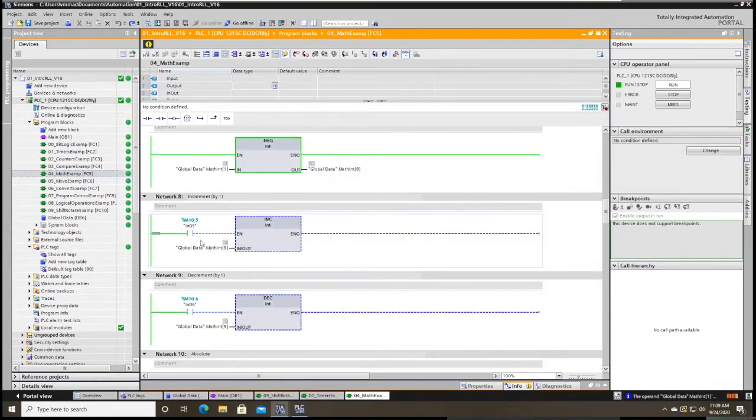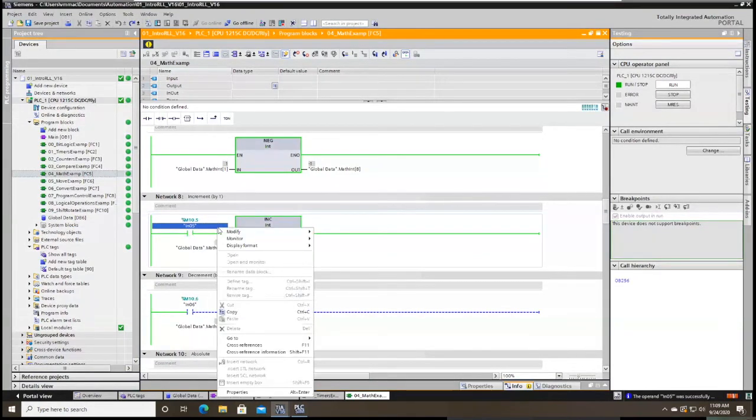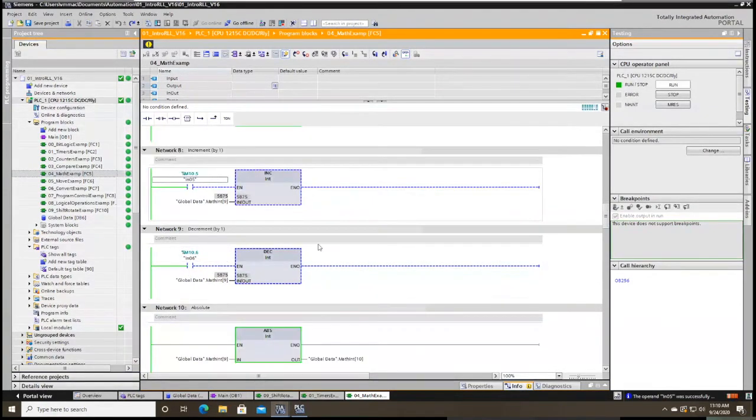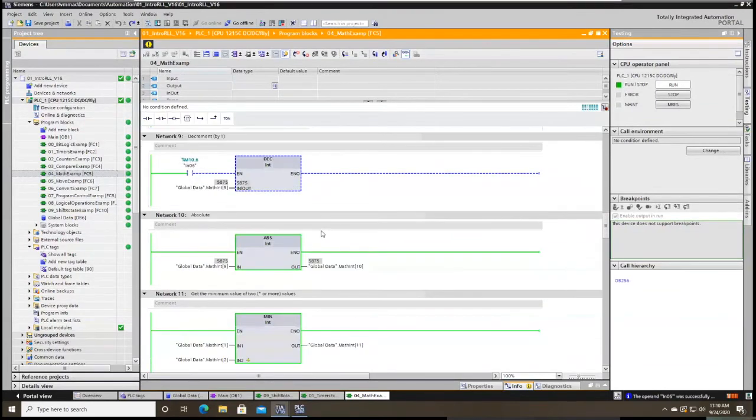There's an increment function. So if this were to go high, it would increment this value defined at the input here. Boom. Oh, it's held high, so it's continually incrementing every scan. However, if it were just a pulse, we'd usually use a pulse for this instance. That way it would see that true rising edge, it would pulse once, it would count by once, and you're good to go. I should try change that at some point in time. Same, there's a decrement function that does the opposite.